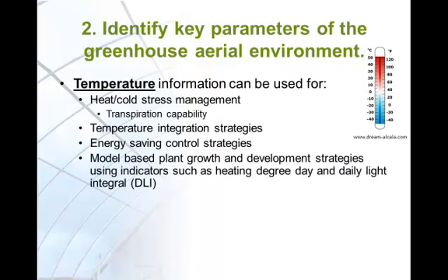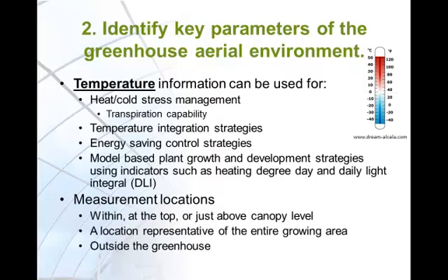Temperature information can also be used to model plant growth and development strategies using indicators such as heating degree day and daily light integral. It is very important to measure temperature at the correct location for accurate results. The reading should be recorded at the canopy level and at a location representative of the entire growing area. It is also important to record the outdoor temperature.